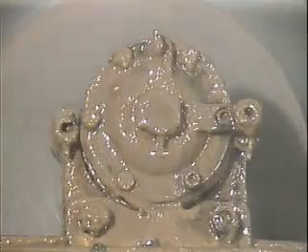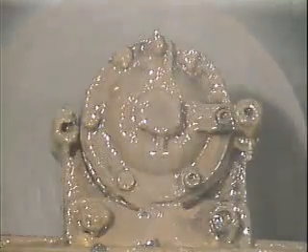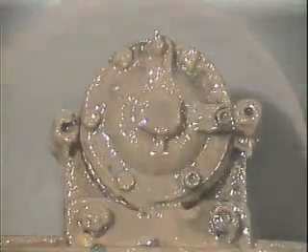The water resistance of a grease is an important property if the grease will be used with machinery that can be damaged by water. Many greases break down or dissolve when they come in contact with water, but most greases that contain thickeners such as calcium or lithium soap, which are insoluble in water, resist water very well.